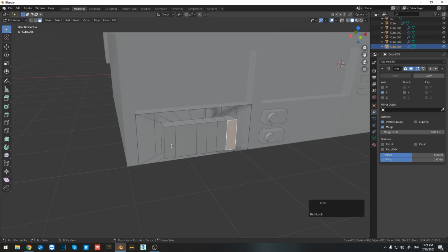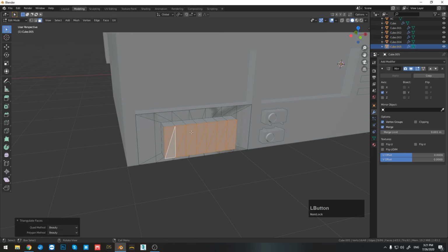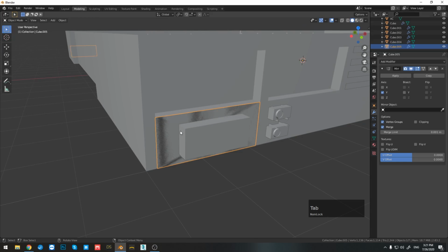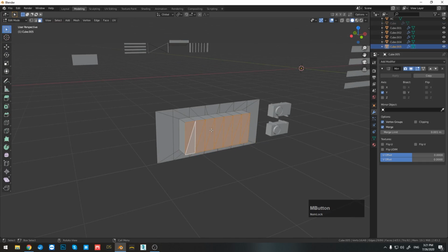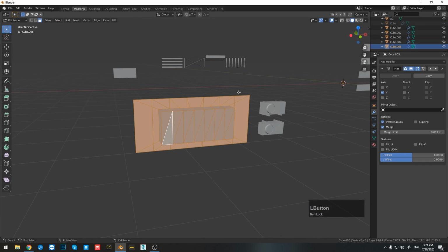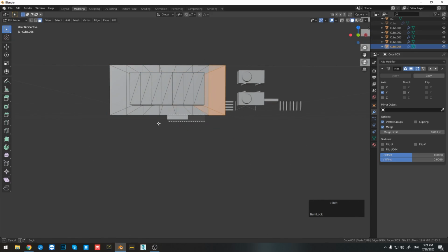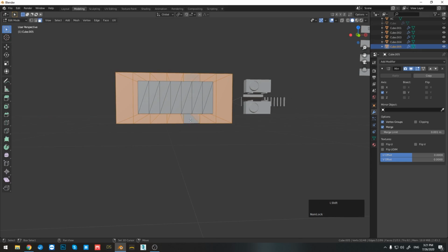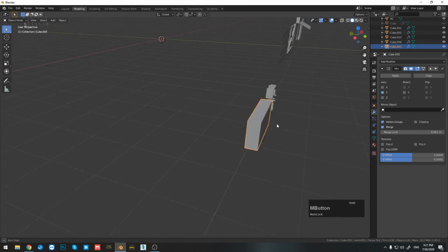Now select these faces right here, then right click and select triangulate where you're in face selection, and then press Tab again to go back. Now hide that mesh, press Tab again here, select everything on the sides that we've made. So let's select all of the sides like this. Then press delete, select faces, so we have something that looks like this.